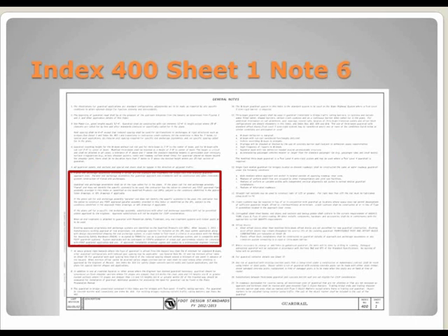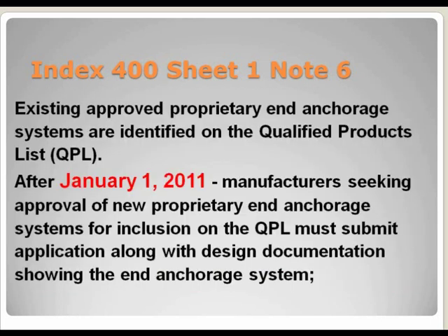Index 400, Sheet 1, Note 6. This note is updated to reflect new AASHTO MASH requirements for crash testing. The existing approved proprietary end anchorage systems are identified on the qualified products list.